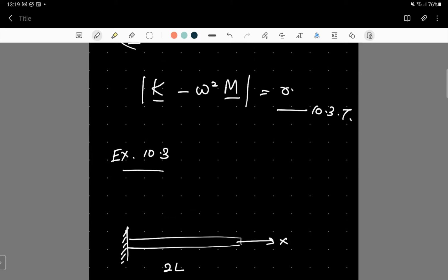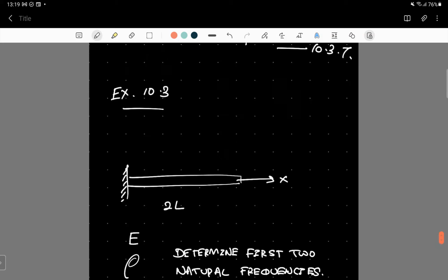For this, we can either use the lump mass matrix or the consistent mass matrix approach. In general, we know that using the consistent mass matrix, the result seems to be more accurate to the ones obtained from the analytical or experimental results than those found using the lump mass matrix method.